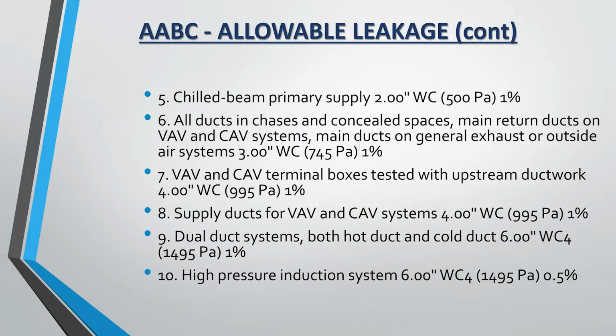Chilled beams. Everybody work with chilled beams? No? Chilled beams are a marvel. I do appreciate them. I like them. But if you don't have the air going to them and you're leaking it, they can be a problem. All duct chases, concealed spaces. I hinted on that a little bit ago about that air handling unit up against a wall, but if you have ductwork in a chase and it hasn't been duct leakage sealed, and we get to a point where it's leaking and now we have a problem, we're starting to tear walls apart and get back in there.